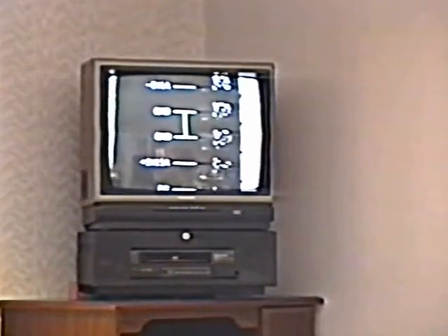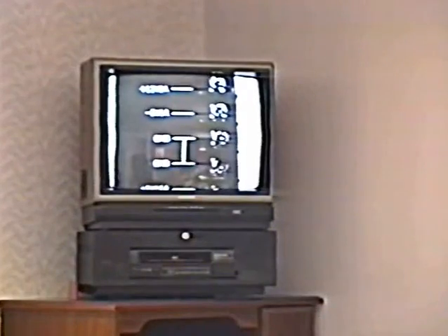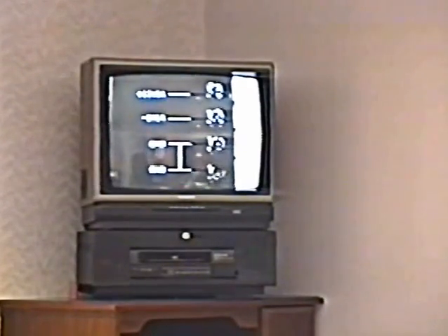The next pin up is labeled plus 5 volts at 15 amps. This one happens to be a 15 amp power supply. And then there's 2 ground connections there. There's another output that's minus 5 and another one that's plus 12. The minus 5 and plus 12 are primarily used for the audio circuits. For instance, the plus 12 usually only powers the audio amplifier. That's all it does. It just powers the audio amp. And the minus 5 is usually also for the sound generating circuits.